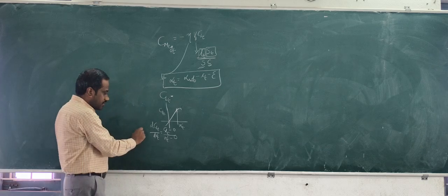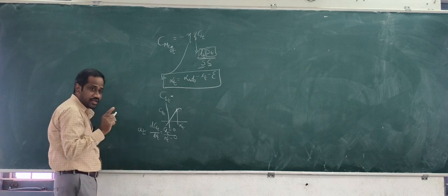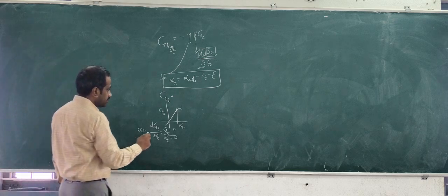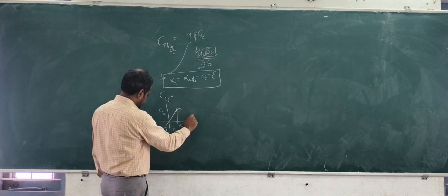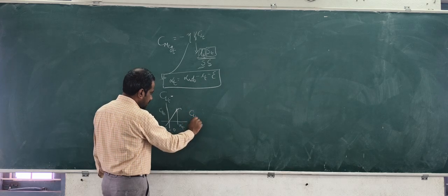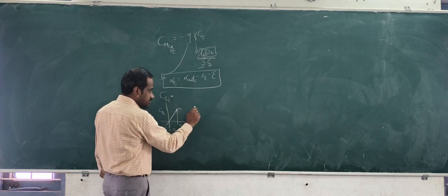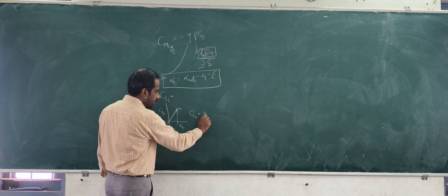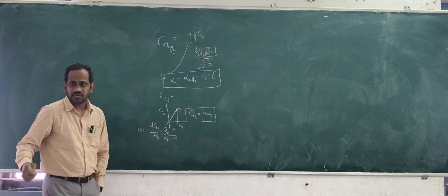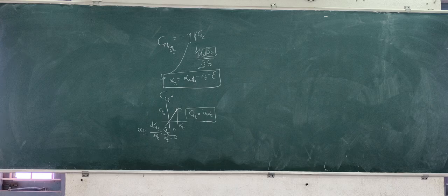So the slope of the lift curve of the tail, write down, can be written like this. Then CLT can be written conventionally as AT alpha t. Is it right? So we know the slope, we know the angle of attack of the tail. So all of them can be written as CLT only. Coefficient of lift can also be written like this.